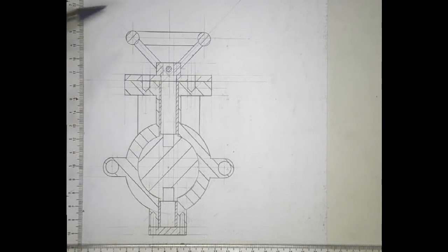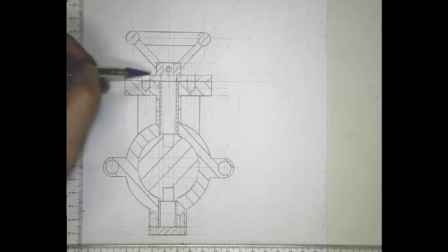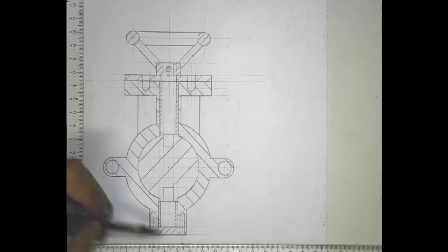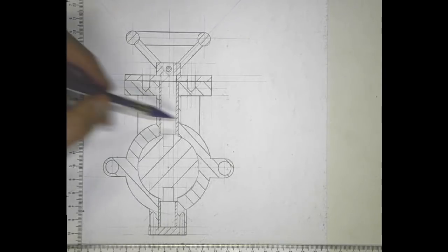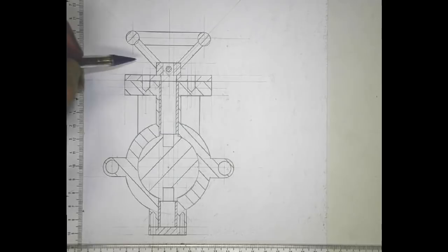And once the sectioning has been completed, the drawing will look as follows. The only details remaining will be the washers, the sizes of which will be read from the relevant tables, and those will then be drawn in. In this case, the bolts or screws have not been specified, so you would not be required to draw those. Just a reminder that webs and shafts, as well as the spokes on this wheel, do not get sectioned as a rule.